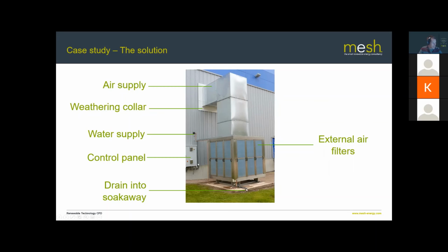You can see the drain coming off here, so there's a French drain along the bottom of this, around the plinth, and every day or so, the automatic valve in the bottom of the sump here would open and drain away any water, and then once the water drained away, there was a period of about half an hour to allow the wetting mats to dry, when the fan would run, and then after that half an hour a valve would open and allow fresh water in.